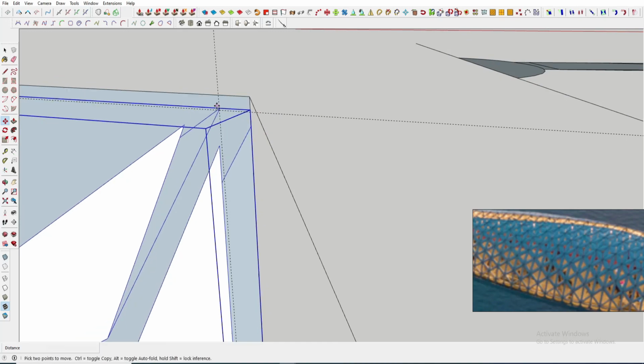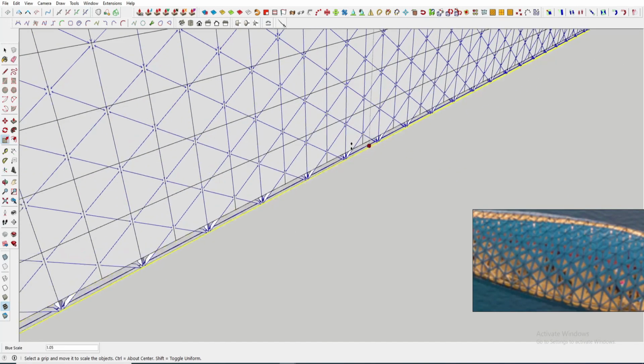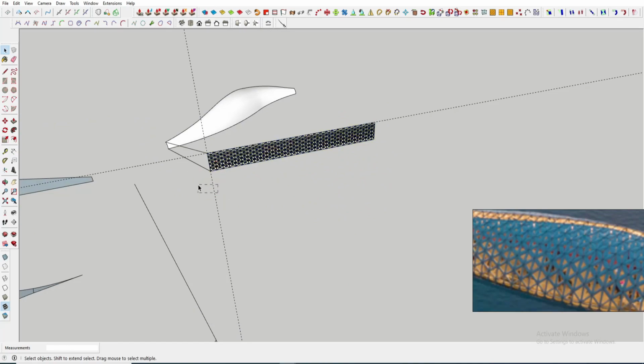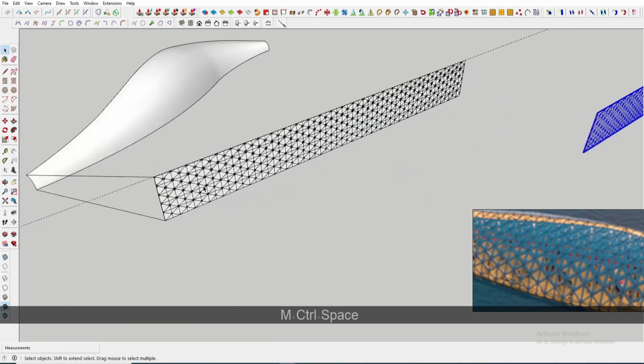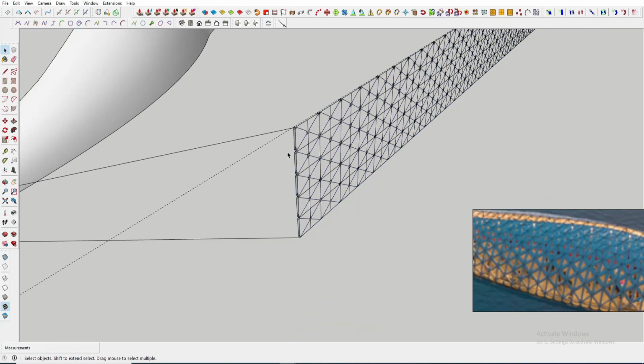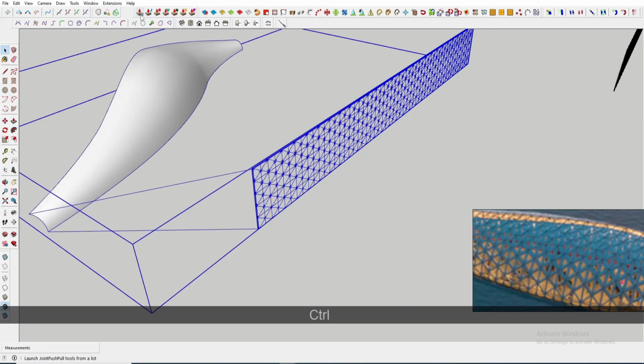So before that we need to align exactly all along the edges, because sometimes if it's projecting outside or inside, the surface will not fill equally, it will not bend equally. Some area it may be going up and down. So before clicking fluidify, you need to align it all along the edges properly.